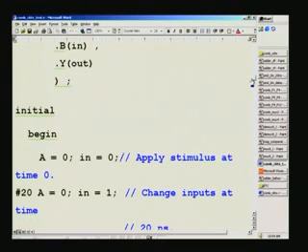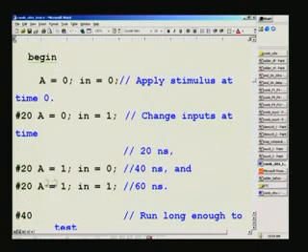That is, instead of this, you use less or equal to here, and then put this 20 before 0. So at that point of time only this will be assigned. And if you had given 21 here, let us say, then at 21 nanosecond only this will be assigned, and so on. And we have also seen earlier what will happen if there was a time scale here.